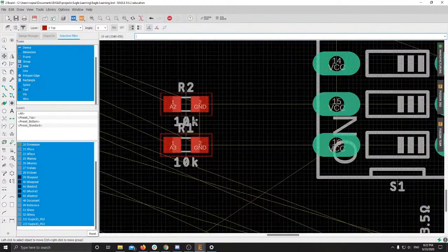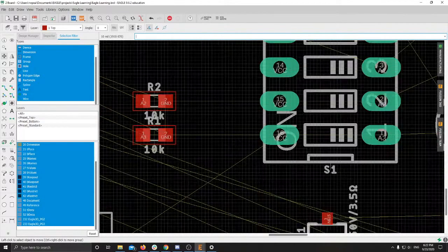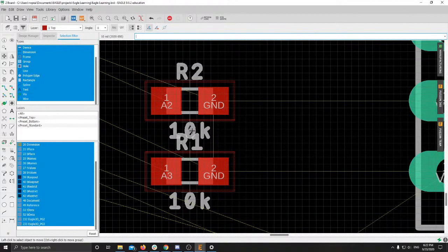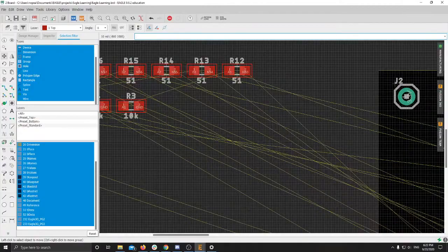So I'm just lining each of these up vertically with each other and then horizontally with this part. One thing to note, you'll see here there's overlap between this R1 and 10K. These are actually printed onto the surface of the circuit board, but it's just text, just ink, so it doesn't really matter if they do that. If it optimizes your layout further, it's definitely worthwhile to do that. Just know that it may be harder for somebody who has seen your board for the first time to figure out what they do without the schematic.